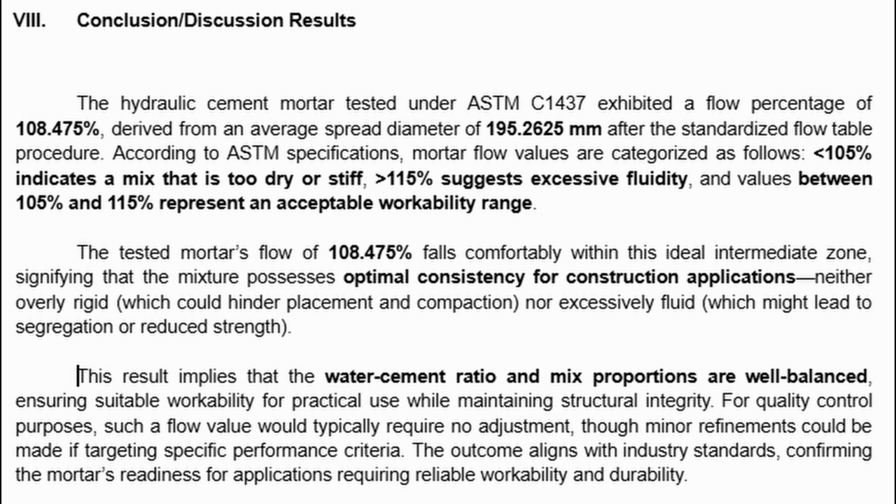segregation or reduced strength. So this result implies that the water-cement ratio and mix proportion are well balanced, ensuring suitability and workability for practical use while maintaining structural integrity. For quality control purposes, such a flow value would typically require no adjustment, though minor refinements could be made if targeting specific performance criteria. So the outcome aligns with industry standards, confirming the mortar's readiness for application requiring reliable workability and durability.